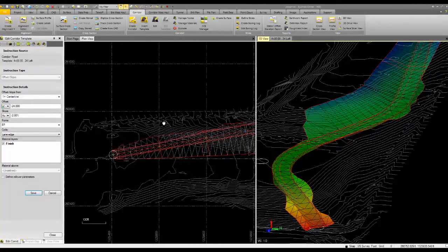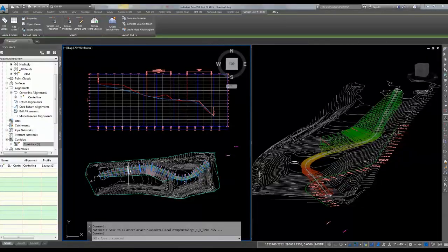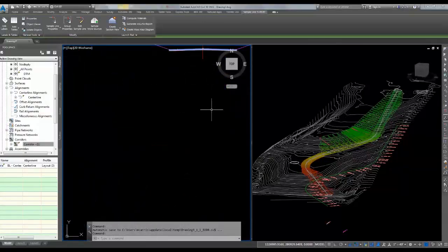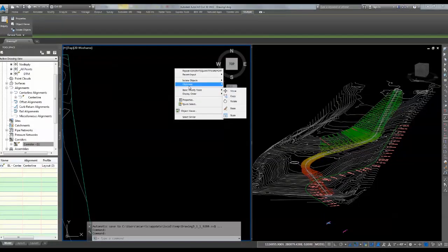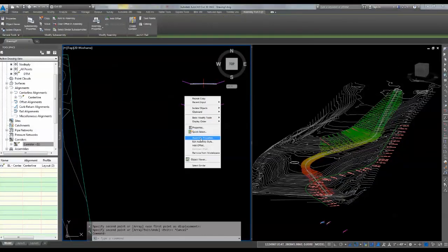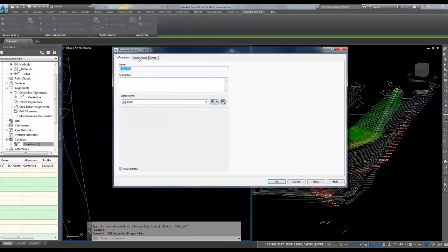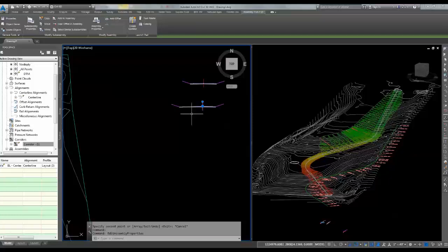Okay. Now to do that over in Civil 3D, it's a little bit more challenging. The first thing we have to do is take this subassembly or assembly, and copy it. Then we're going to go in and edit the assembly properties by taking that left basic lane transition, making it 24, and now we've got that one built.